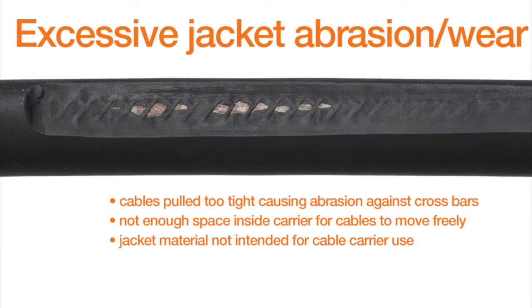That's one of the big ones, because a lot of times if you're looking at a static cable or a flexible cable, because of their purpose, they're not specifically designed for the continuous flexing aspect. So that's usually where we run into the issue of the wrong jacket material, is when you've spec'd in or looked at the wrong cable based on the industry.